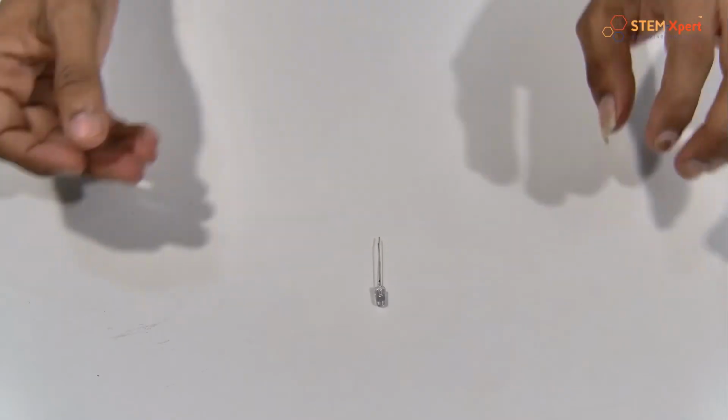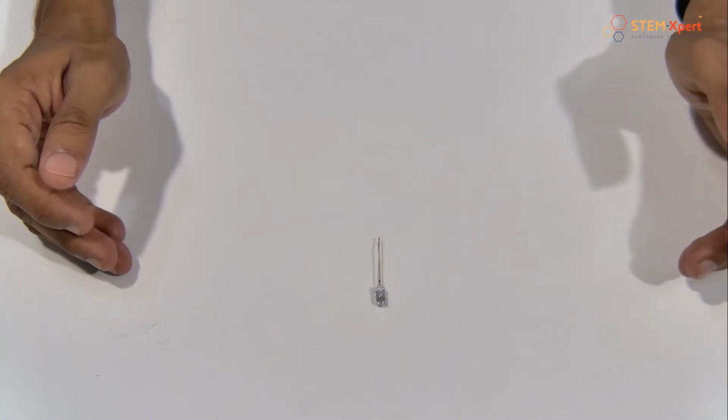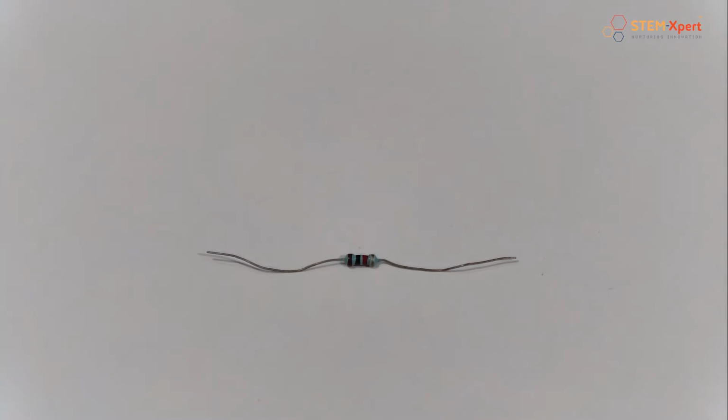Okay, so now let's discuss what a resistor is and what the function of a resistor is in this circuit. So this is our resistor. Do you know the purpose of the resistor in our circuit? Okay, if we connect the LED directly to that 9-volt battery, then what happens? Exactly, the LED would definitely be damaged, right? Yes. So in this session, we are using a resistor to reduce the flow of electric current. Basically a resistor is an electrical component that is used to reduce the flow of electric current in a circuit. Here we are using a 9-volt battery, so the resistor can resist the unwanted current from the 9-volt battery and our LED is safe.